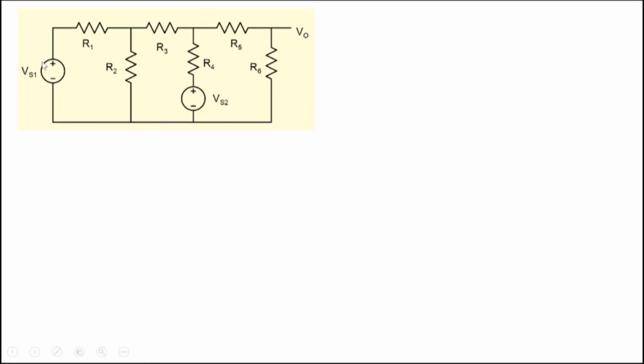So in this case, we have two sources here. So V0 is obviously dependent on VS1, and V0 is dependent on VS2. And in this case, as you would expect from a linear circuit, the dependence of V0 on VS1 will be linear. So V0 is, let's say, K01 into VS1. But V0 would also depend on VS2. These are two independent sources, so K02 times VS2 here. So both these relationships are linear, right?